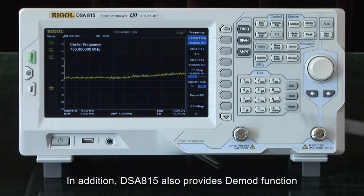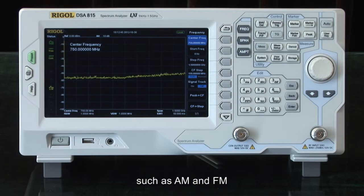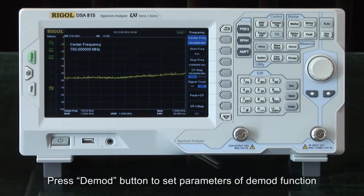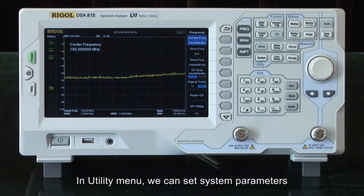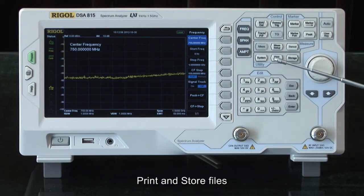In addition, the DSA-815 also provides demodulation functions for AM and FM signals. Press the Demod button to set the parameters of the demodulation function. In the Utility menu, we can set system parameters, print, and store files.